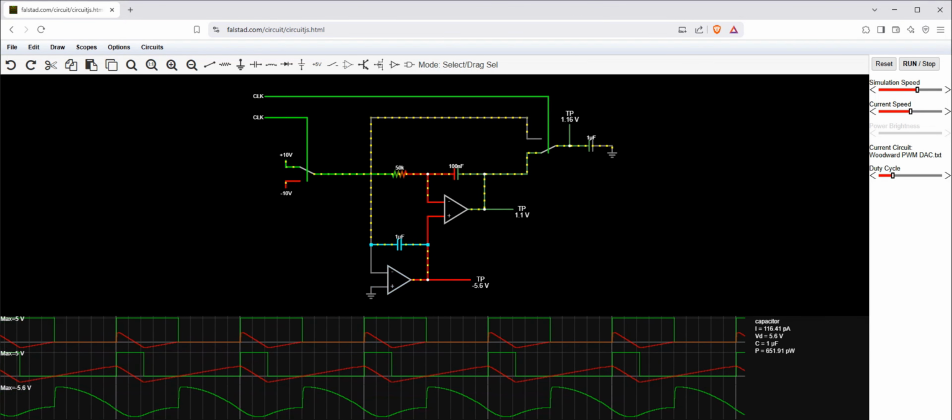Surprisingly enough, the idea of feeding a sampled version of the integrator waveform back to the summing junction is not a Woodward original. This method is first described in a paper from 1970, which calls it sectional average integration. This paper was thoughtfully cited by a similar EDN design idea, although this one does not feature feedback of any kind. HP used this sectional average integrator circuit in 1976's HP 4261 to accurately measure the average of a non-DC waveform. What I found particularly enticing about the Woodward version is the claimed one-cycle settling time.